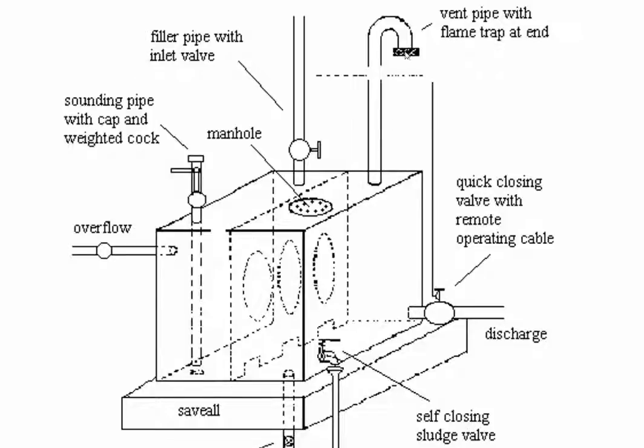So on our breather, we're going to have a flame trap, which is basically a gauze which will impinge the flow of flame. If we get any of these vapors ignite, then it won't propagate back through to the tank. We're going to have a look at some other breathers as well. Sometimes we've got a type of valve arrangement to prevent water getting in through here as well.